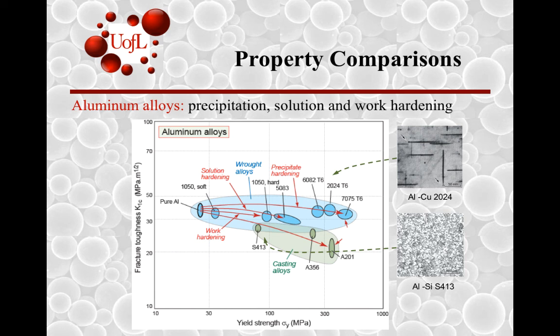So you change composition, you change the microstructure, you change the property space, and you change not only properties in terms of the end use, but properties in terms of being able to manufacture them differently. So casting alloys, basically the melting characteristics, end up becoming very different.